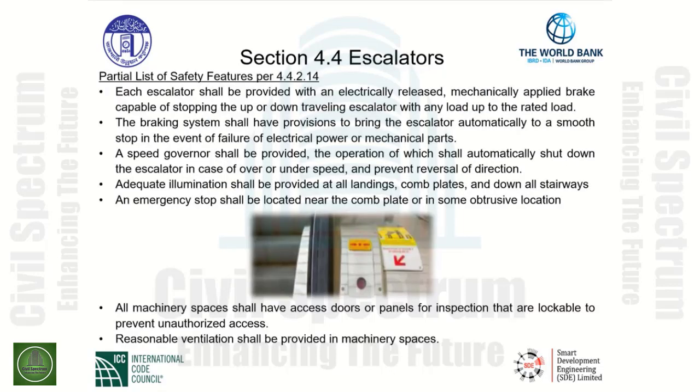A partial list of safety features according to section 4.4.2.14 is given here. The first item in this partial list is that each escalator shall be provided with an electrically released, mechanically applied brake capable of stopping the up or down traveling escalator with any load up to the rated load.